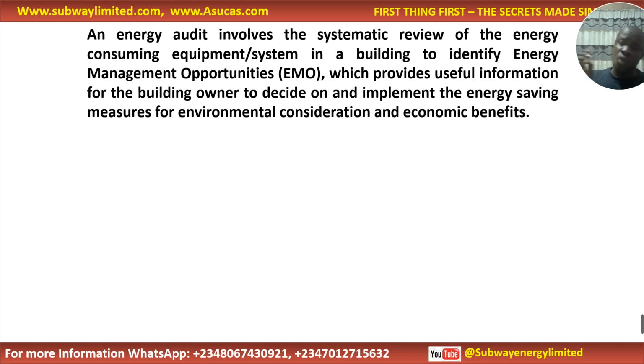So when you go for a power audit, you have to look at the energy management opportunities that will help you cut down on the cost of solar system installation. And most times you can think of load shifting, that is powering some of the electrical load with other power sources. You can think of running some of the electrical load during the daytime. All these are different energy management opportunities that you can think of. So power audit will give you all that information when you visit the site.